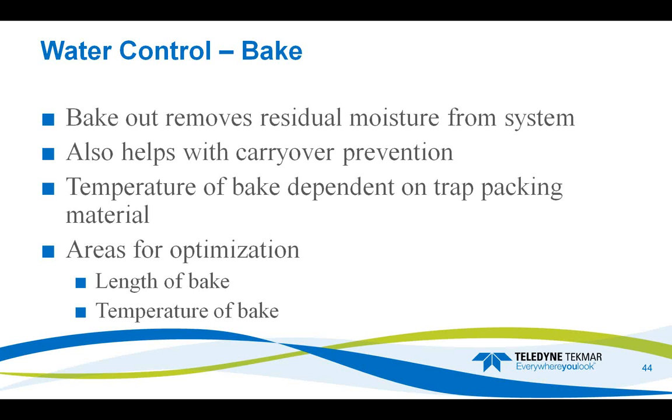And just like we mentioned earlier, our bake out is also going to help with carryover prevention. The temperature we use for bake is going to be dependent on our trap, so we're going to want to make sure that we don't overheat our packing material, causing breakdown of our adsorbents. And then our areas for optimization here would be our length of our bake and the temperature of bake.